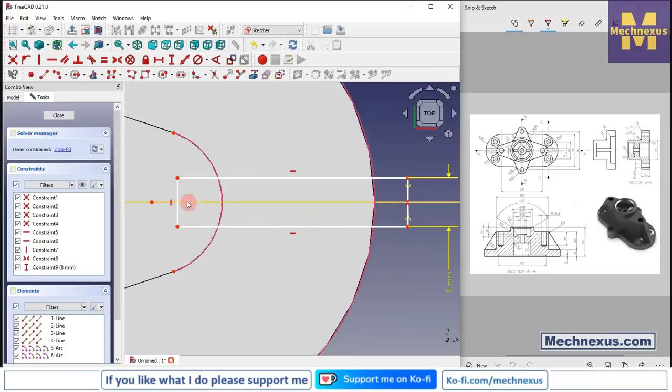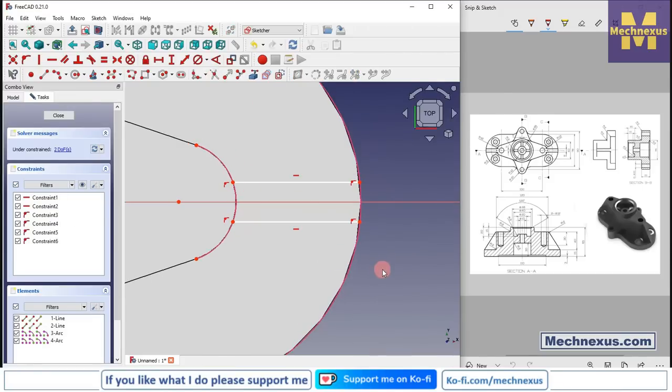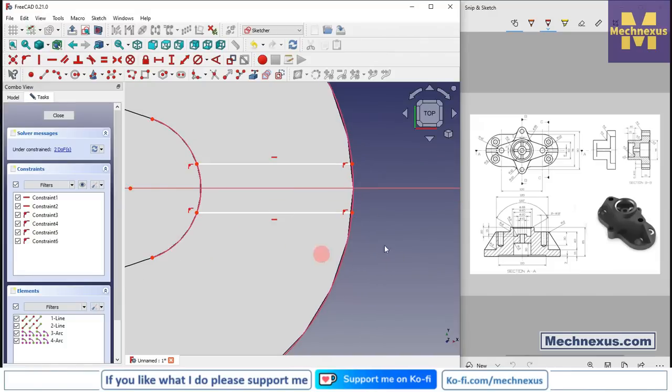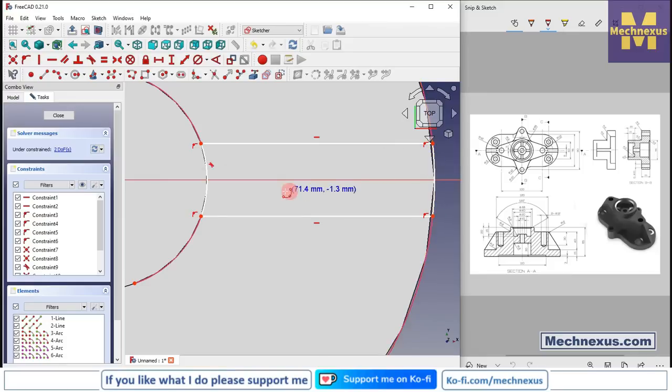and here we will delete this line and delete this line, and we will use the trim tool to remove the unnecessary geometry, and because of the trim our dimension has gone, so no issue. So we will use a 3-point arc and create an equal arc, select a 3-point arc and create an arc.